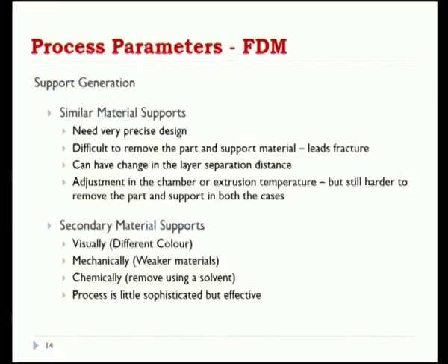In that time, the product may be smaller, but the supporting structure may be much higher. So he needs to concentrate on that perspective while developing AM products. It is important because even if one support structure is missing at a particular point, there may be deviation in a normal product development.